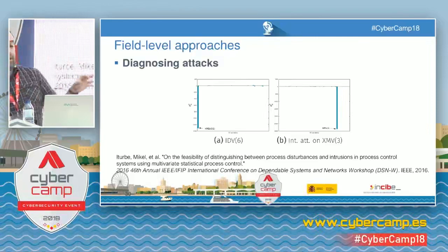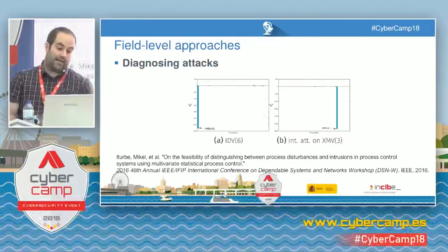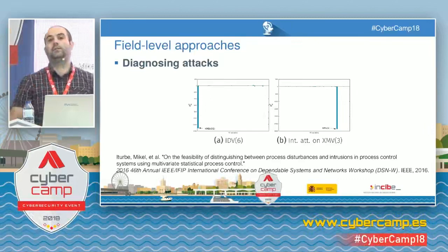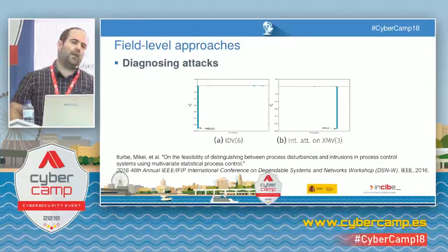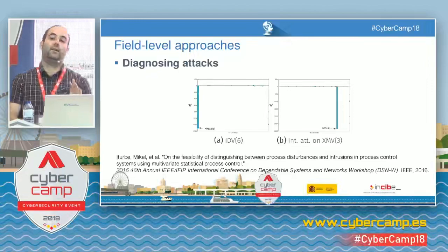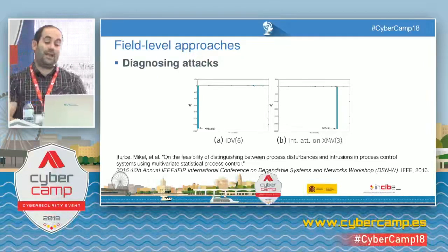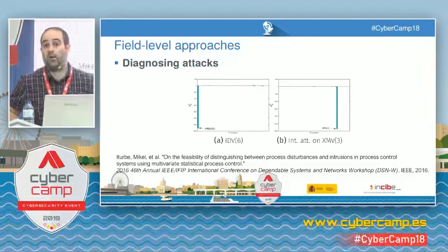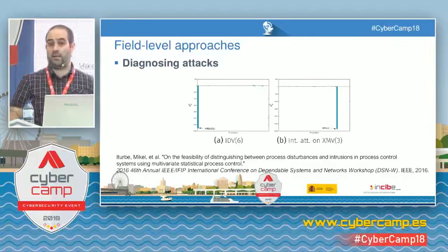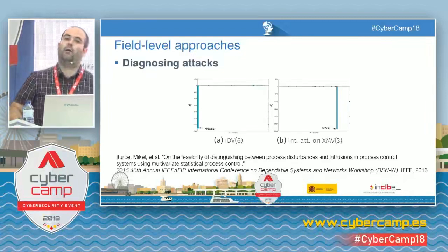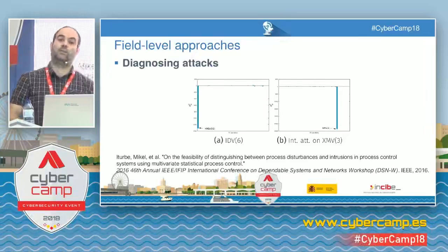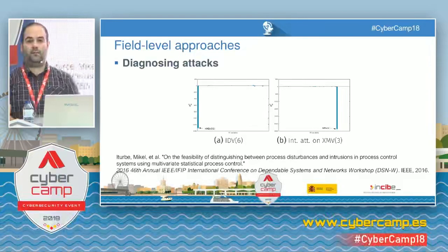With some graphs, on the left side you see there is a negative bar, which is a large one, stating that the incoming flow is lower than it should be. And on the right side, what we see is that the opening ratio for that valve is way lower than what it should be. So it is closed. Interesting, isn't it? We can see if there's been a malicious attempt to close the valve, or maybe not.